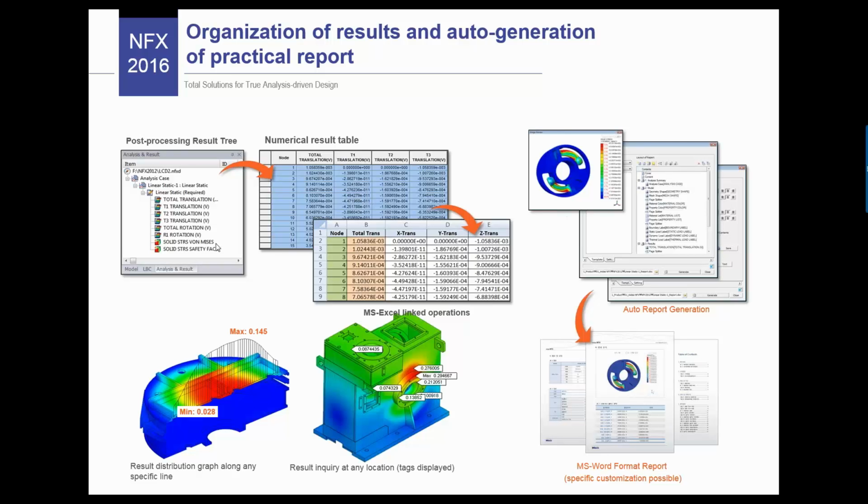Now I have finished talking about the analysis types, and I still have a few slides about the post-processing functions. midas NFX allows you to export your results into different formats. You can of course view them in tables and export to Microsoft Excel directly from the software. You can also view results directly on the model, on a curve diagram like that. It's very impressive. And you can use the probe tool to probe the results at any point of the model.